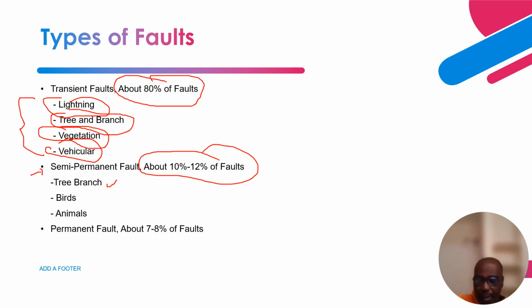It's not the situation where transient faults were due to high velocity winds and the tree leans on the feeder conductors and reverses back to its original position. This one leans on the feeder conductors and stays there until patrol operators find the tree branch and move it back or cut it down.